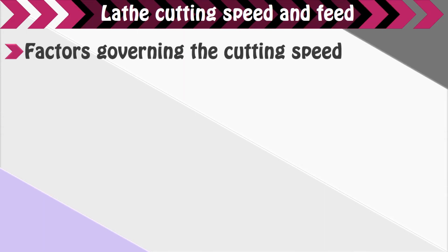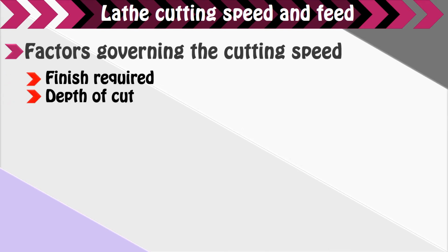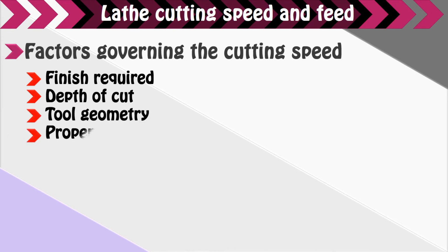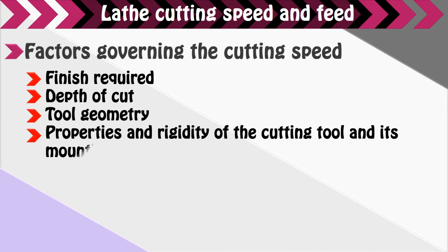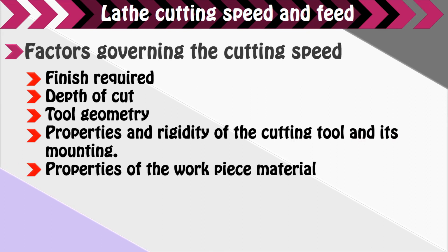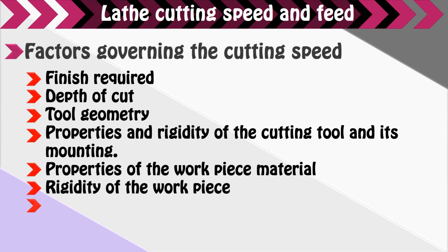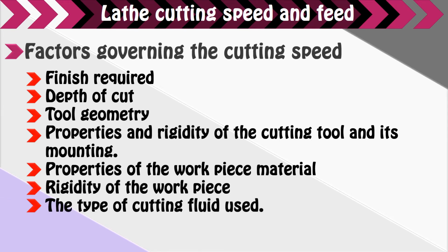Let's see about factors governing the cutting speed. Finish required. Depth of cut. Tool geometry. Properties and rigidity of the cutting tool and its mounting. Properties of the workpiece material. Rigidity of the workpiece. The type of cutting fluid used.